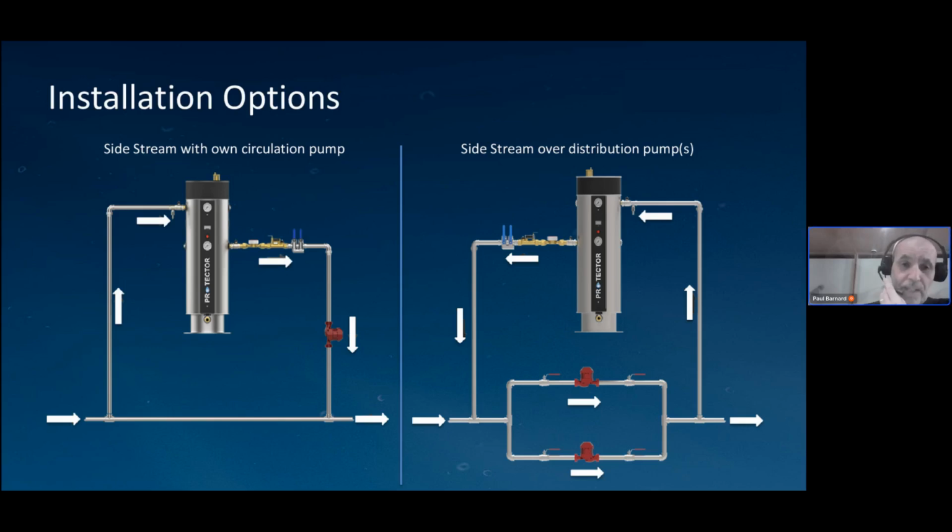In terms of installation of this unit, this is normally installed on the hottest part of the system to help vent the air out on side stream. So we manage the flow rate through the unit, ensuring we see a system pass of water over a 24-hour period.